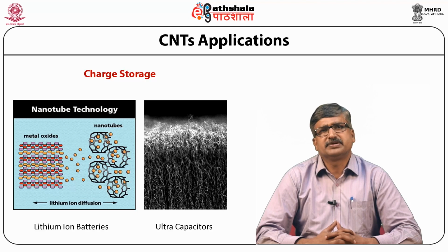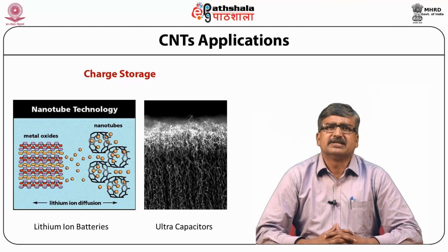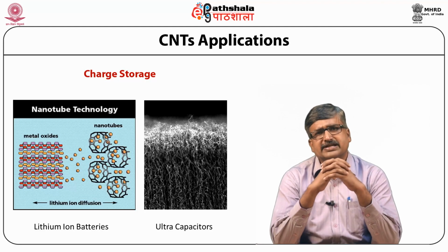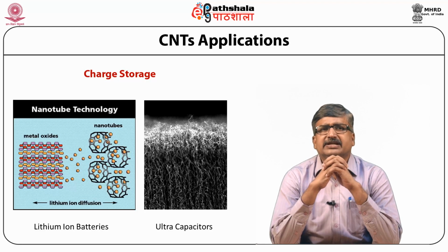They have a number of properties, including high surface area and thermal conductivity, which make them useful as an electrode catalyst support in PEM fuel cells, which are proton exchange membrane fuel cells. They may also be useful in gas diffusion layers as well as current collectors because of their high electrical conductivity. CNT high strength and toughness to weight characteristics may also prove valuable as part of composite components in fuel cells developed in transport applications where durability is extremely important.